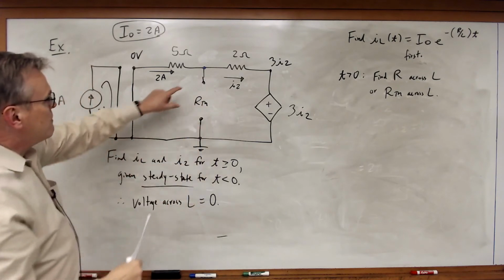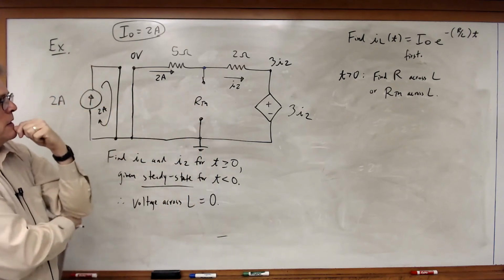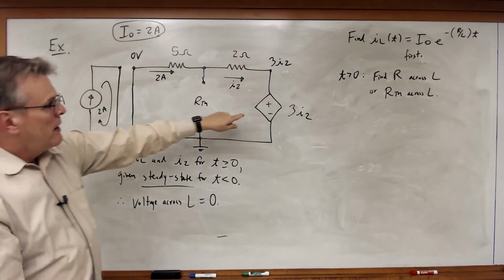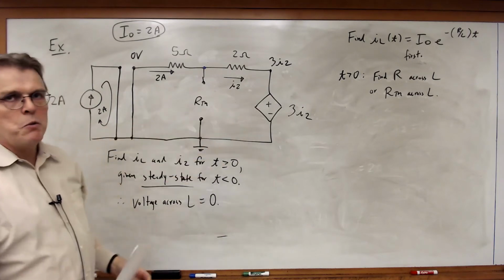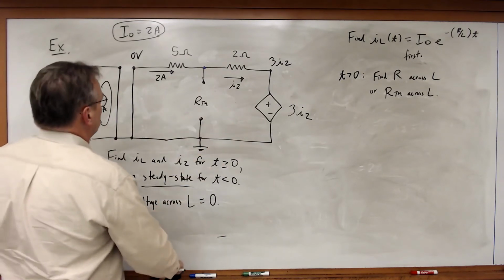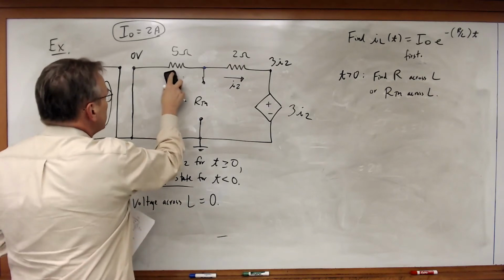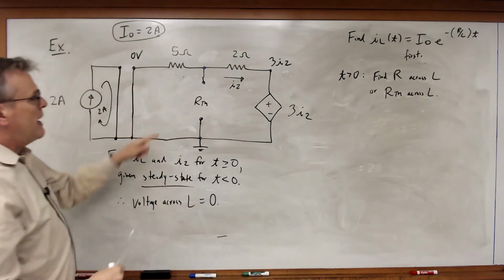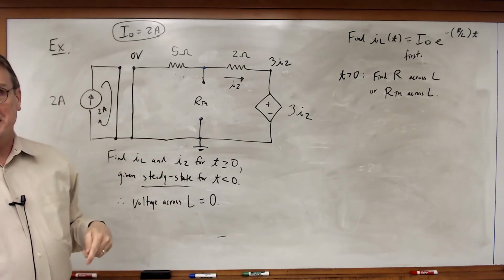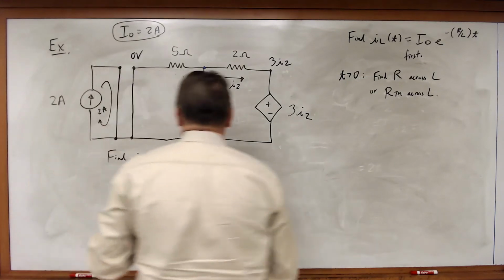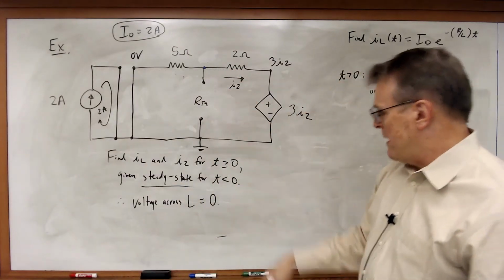I want to know the Thevenin resistance between those 2 points. There's only one problem here. Now I have got a dependent source. I can't just add resistors together. So in this case, I have to go through and apply the source driving technique. All right? So let's apply source driving to this.